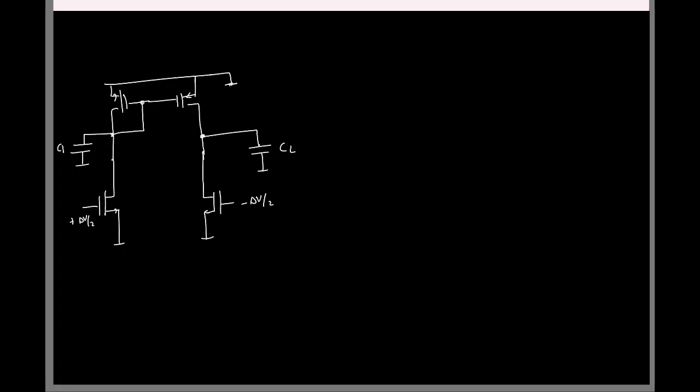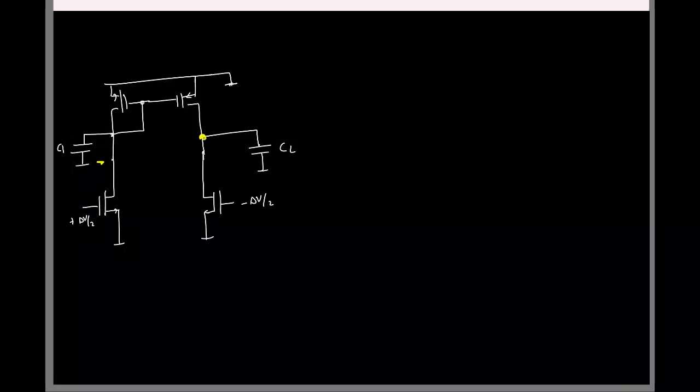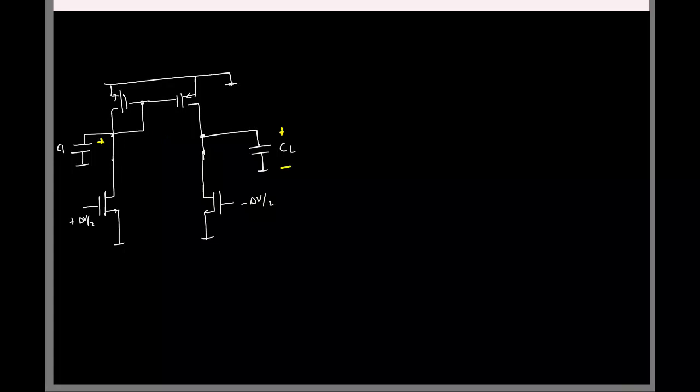Okay, so how many poles and zeros do you think we have now? They have two capacitors. Can I set the initial conditions on the two capacitors independently without any contradiction? Why or why not? If I set the voltage here, I can set this voltage here. What's the problem? This node is not coupled from this, right? There is no relation between these two nodes now actually. With respect to initializing the capacitor voltages, I can have two independent voltages set there. Is that fine? Only if they are coming in parallel or series, I cannot do it, right? Here they are two different nodes, I can do it without any problem.